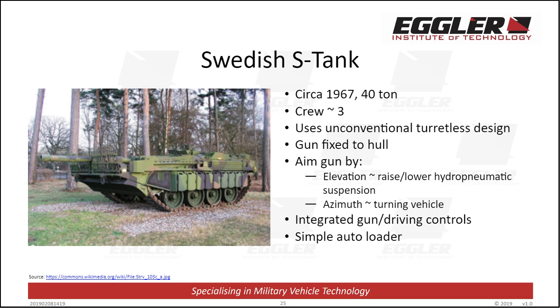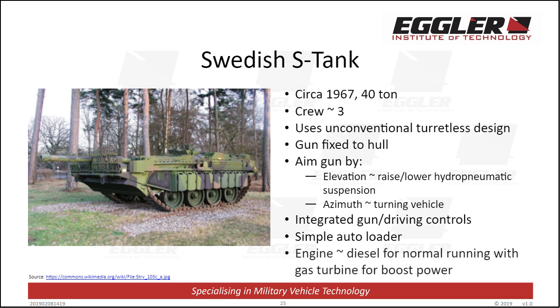The other novel aspect of the S-tank design is that it used a hybrid diesel gas turbine engine. This particular engine arrangement provided for very high mobility as the gas turbine, which has very desirable torque characteristics, can be used at low vehicle speed in difficult going to provide excellent mobility. But when the vehicle is stationary, or the engine was operating at part load, the diesel engine kicked into operation to provide high fuel efficiency. The S-tank is a very nice but complicated design.